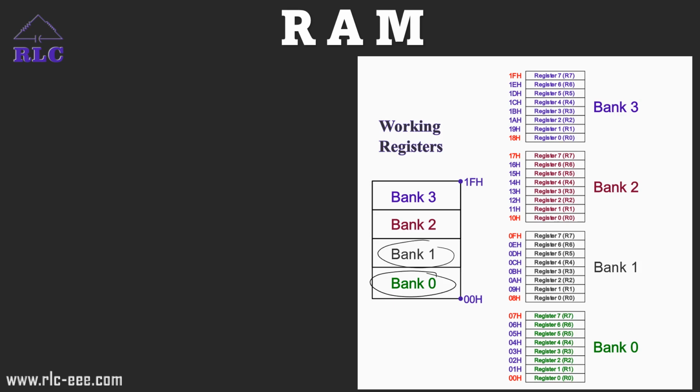Because R0 is the name for 00H, and also for 08H, 10H, and 18H. If I say move the data from R0 to A, the microcontroller has to choose which of these 4 memory locations to pick.